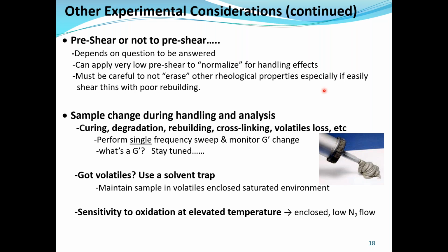But we need to be mindful that we don't want to erase some other rheological properties, especially if the sample really easily shear thins and has very poor rebuilding. The sample may change over time during handling and analysis. I have some studies that run overnight, a good many hours, as the sample is curing. Is it degrading, is it rebuilding and crosslinking, is it losing volatiles? So we will perform a single frequency sweep and monitor the G prime, which is the elastic modulus, to see if that changes. You may ask, well, what's a G prime? Well, stay tuned, we'll talk about that. By the end of this, you'll have a much better idea.